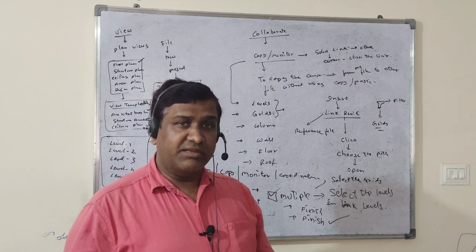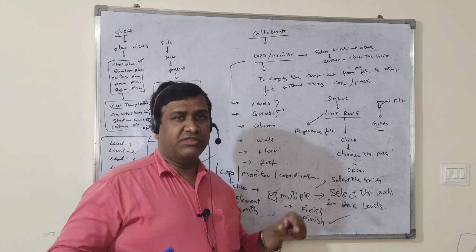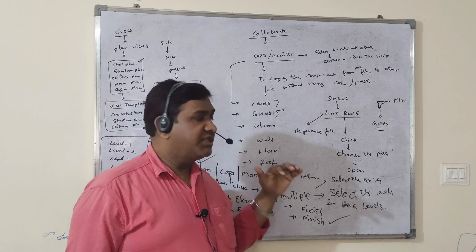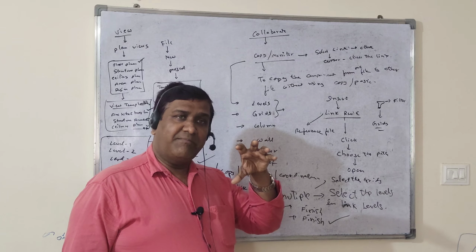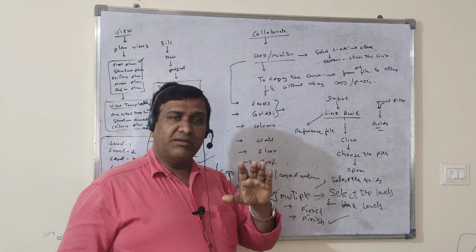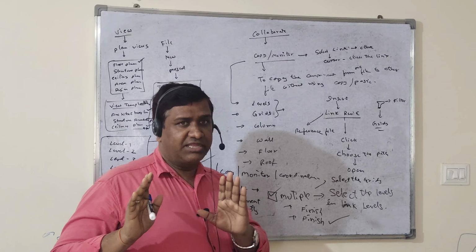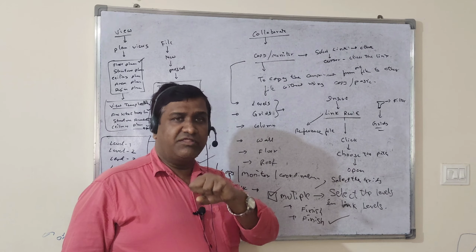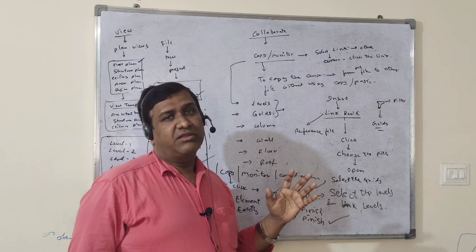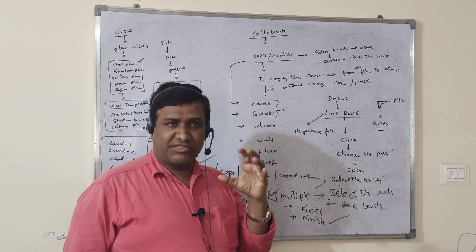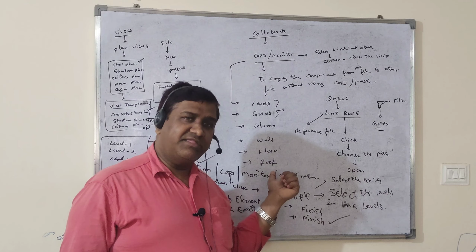Okay, so like that, the columns, walls, floors and roof also we have to copy monitor, because some MEP teams require columns, so they will take the columns. They require walls, so they will take the walls. They require floors, they will take the floors. The architecture team has already developed the model, so all the walls, columns, everything will be there in that model. They make the same columns and walls copy monitor and insert them into the MEP project, because for some design or calculation purpose the MEP team requires them.